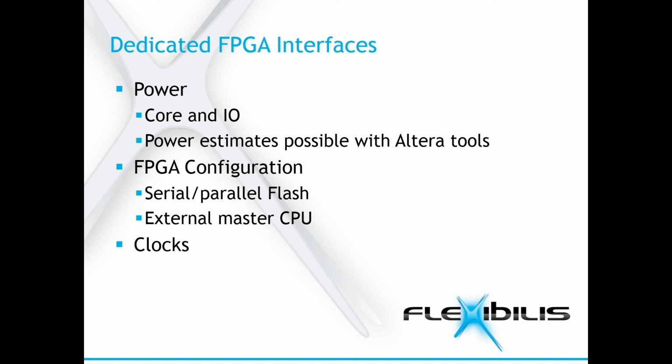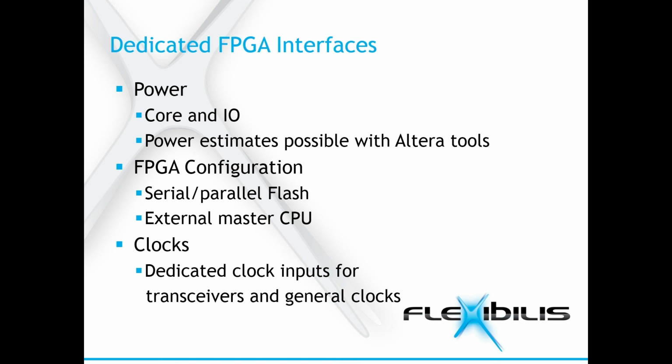The clock signals connected to the FPGA should always be connected to the dedicated clock input pins. In case of FRS, this includes the clock from the onboard oscillator and the interface receiver clocks.